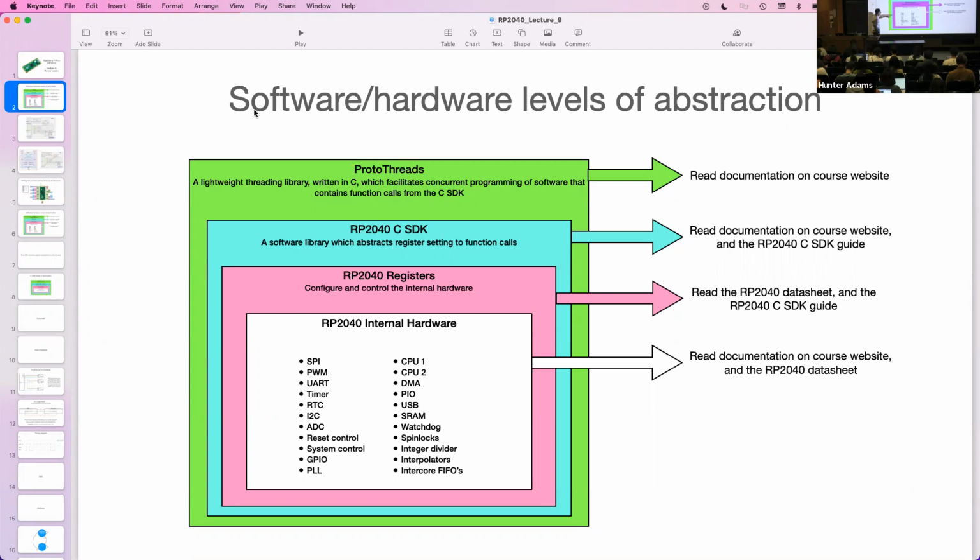So for example, there would be some control register associated with the SPI channel that sets up things like the baud rate, sets up things like the clock phase and clock polarity. And there would also be some status information in the SPI registers that indicate things like the transmission is complete. So you can go check the value of that register to see when the hardware peripheral that you've asked to do something is done doing that thing, right? So all these registers, they're just places in memory that the system interprets in a special way. But they're just places in memory with addresses.